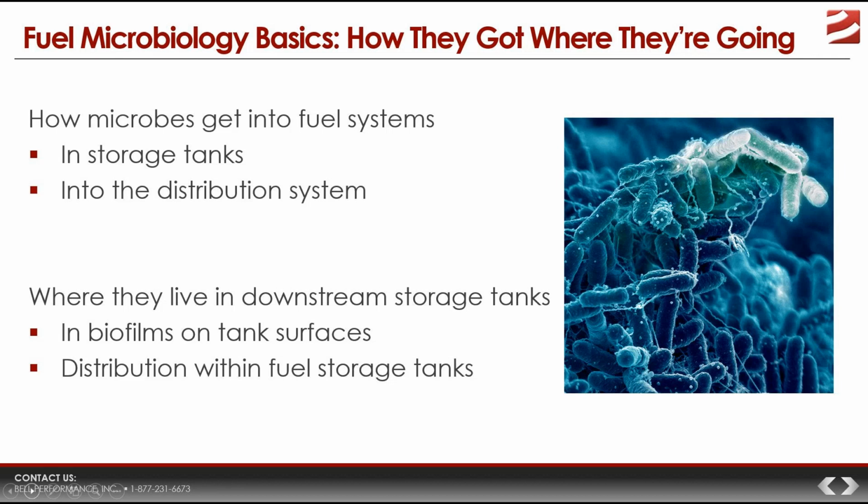Now, when you're talking about microbes getting into fuel systems, there are two considerations here, two areas to look at. How do they get into storage tanks, and how do they get into the broader distribution system? Well, for storage tanks, there's lots of ways. Anything that enters a storage tank will have some level of microbial growth associated with it, whether it's the water vapor and the dust, which you can't even see, but it's in the air that's going in and out of a vented tank.